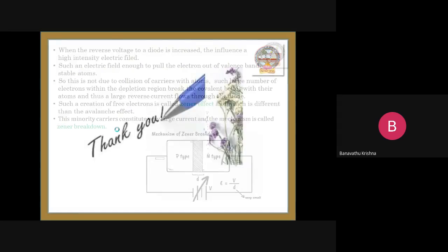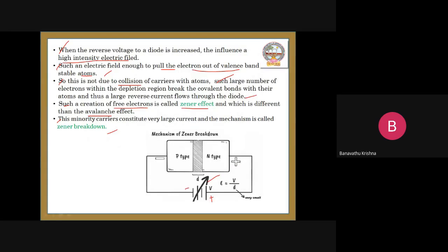Okay, this is the overview of the junction capacitance of the PN junction diode. There are two types of capacitance based on the biasing condition, transition capacitance and diffusion capacitance. We also saw how the transition capacitance is generated across the junction, and how the transition and diffusion capacitance exist across the junction. The transition capacitance is very small compared to the diffusion capacitance because of the concentration of charge particles. Similarly, there is another mechanism concept, the breakdown mechanism concept.